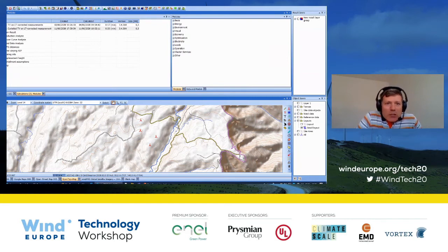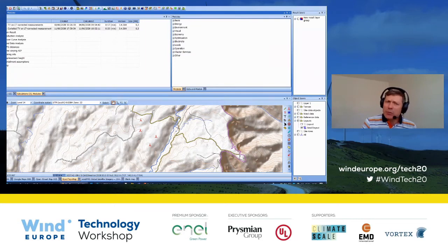So the first question comes from Jon Goldenbeld and asks, I normally apply curtailments in losses uncertainty module, so I can easily export results to file and get nice overviews of separate losses due to each category. How is the curtailment reported if I apply it in the turbine object directly? And the same for if I then also use time varying annual energy production calculations.